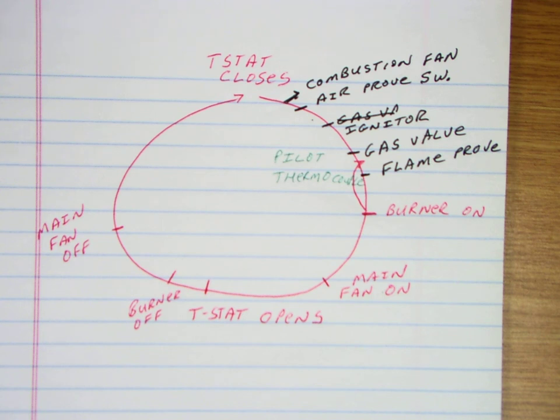The air proving switch tells you that yes, the air is moving, so if there was any leftover gas in there, it's all blown out, it's all cleaned out. The pilot light made sure there was no buildup of gas, because if there was a buildup of gas, it lit, right? There was a standing flame there. We don't have that, so we have to make sure that we've got any leftover gas moved out before we start the igniter, or we could have an explosion.